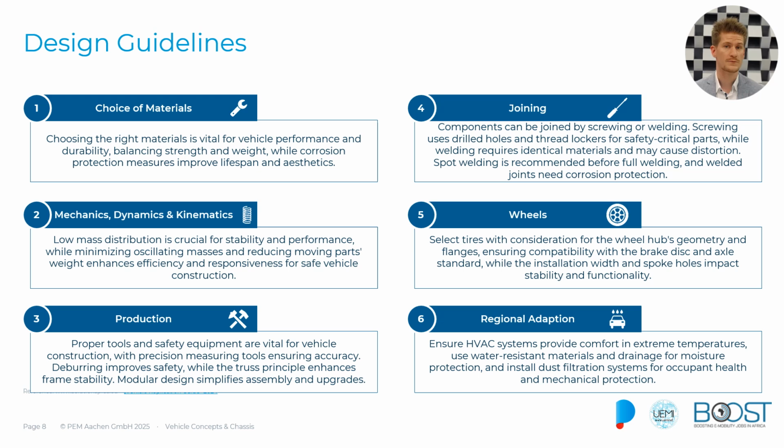Another option might, for instance, be screwing or bolting, which is very easy to do, also in the assembly process, but also in the disassembly process, and might therefore also be something to be considered. So always think about the production and the joining method and what it will do to your vehicle later on.